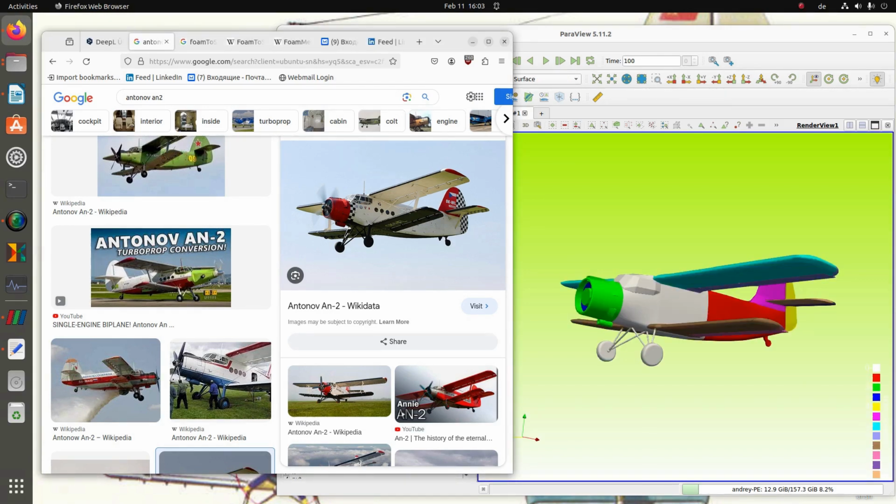We have created in total 4 meshes, 2 for each geometry. With these meshes, it is still possible to start the CFD calculation. For the export of the meshes for Fluent or Star CCM+, we can execute known commands. On the one hand, foamMeshToFluent, and on the other hand, foamToStarMesh. I think our session has come to an end. For further questions, I am at your disposal. You can find my contact details at the end of this video.